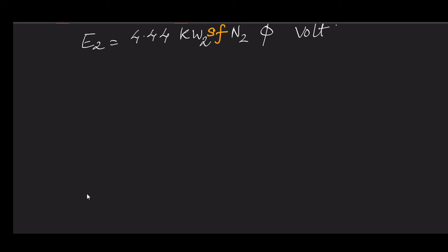Well, so this is quite like a transformer primary secondary equation. The only thing is that you have something proportional to your slip. So instead of writing E2, if we consider that E2 is the standstill induced EMF, we can write it like SE2.